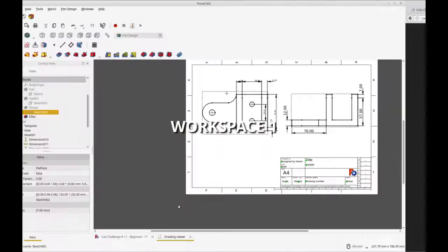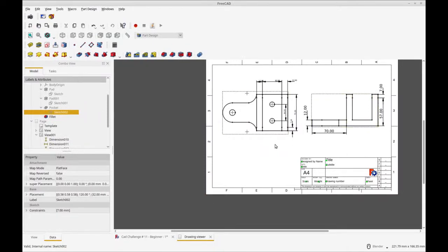So you'll see when I go back to FreeCAD, you'll see our draft drawings are very similar. There's some differences in arrows and stuff, and I didn't get nodules here in TechDraw, where the holes go through. So like this indicates transition. I think like this is where the center point of this hole is. So you see I have two holes here, but I didn't get the center point, so I don't know why that is. So I wasn't able to add that measurement. So if somebody knows how to fix that, or knows how to do it, or why it's broken, put that in the comments so we can have a good workaround.